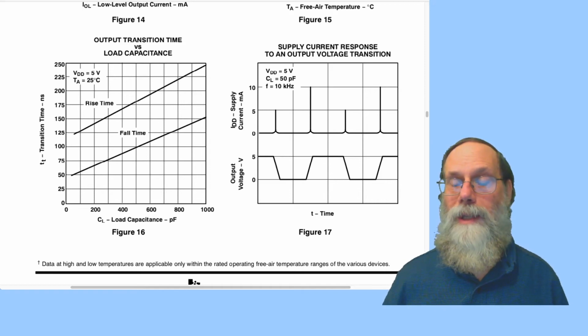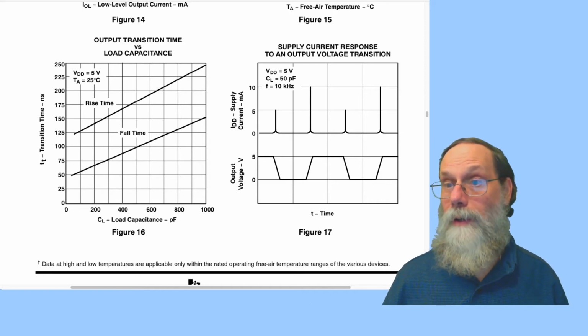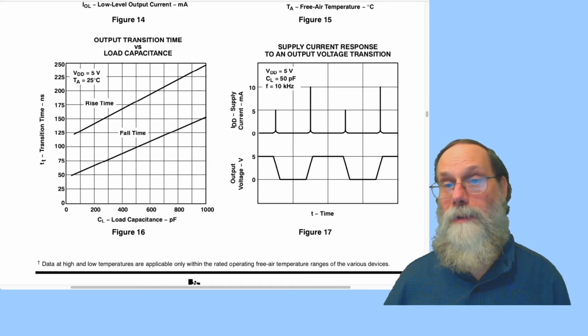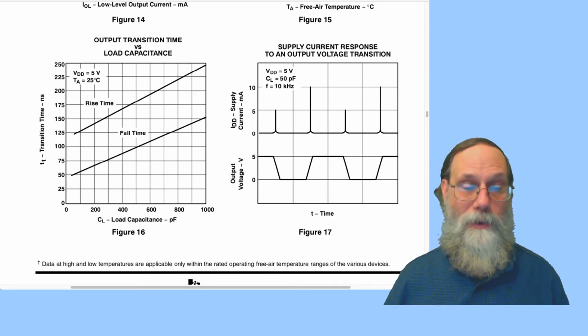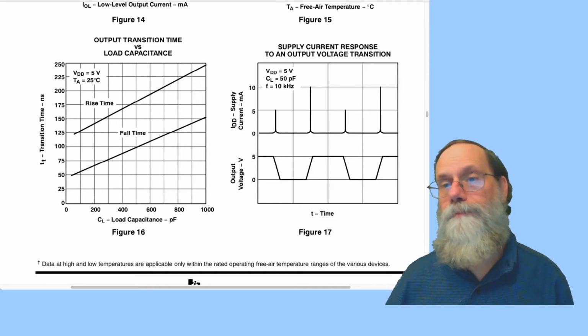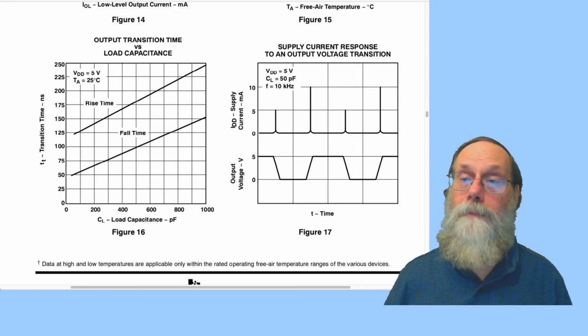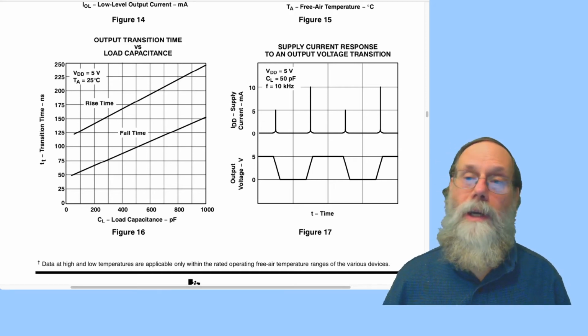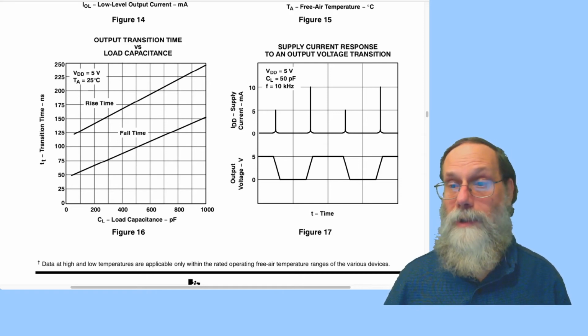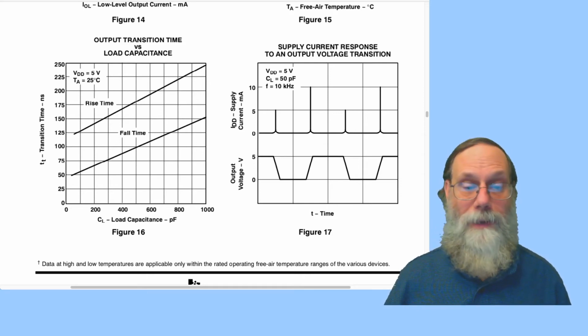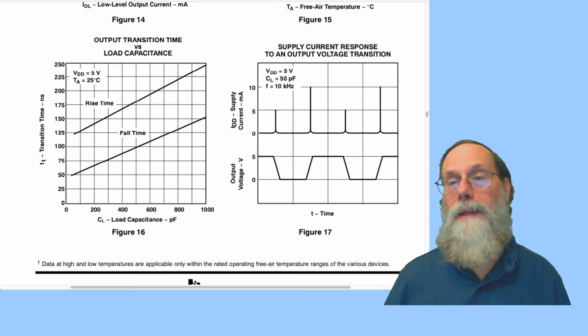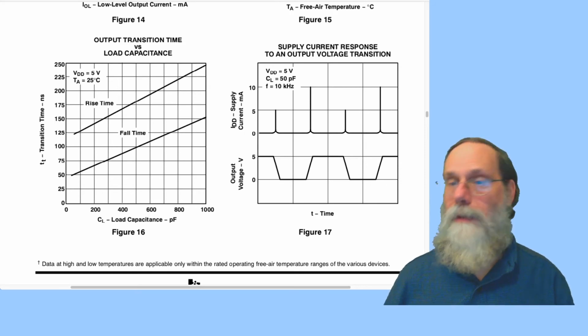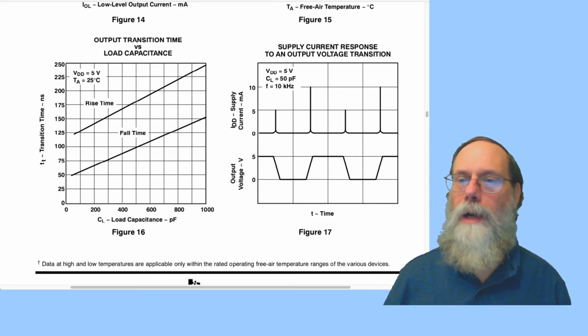If we're looking at a nanofarad or more, you can see that the slope of that line matters quite a bit. This is probably the best estimate we'll have of the transition times. So when you've got a data sheet that provides this, it's going to be a better way to get the estimates than using just the R on or R off.